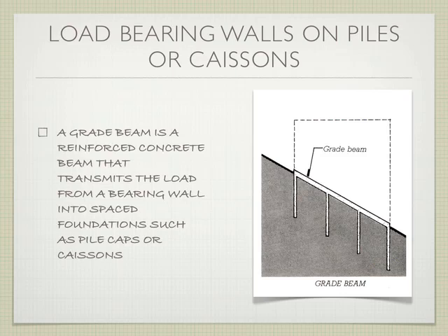And so we drilled all those, and I think we put 105 cubic yards of concrete into the ground before we did any of the actual stem walls, which is an incredibly large amount of concrete for 7 units. But all of those did exactly this. It was a flat lot, right? But we had these piers that were all tied together with beams, right? And so the piers, or the caissons, or the piles, in any case, were using the friction of that against the soil to hold the building in place.